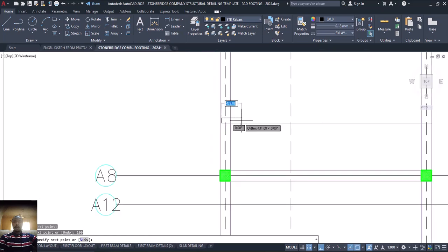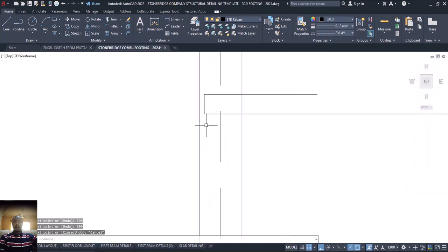Then come inside. Now this inside is what? 600. That's 50D. Is that okay? 50D. So I will now press my what? 600. Is that okay? Enter. Is that okay? At this edge. So now if you look at this one, if you have 25 down plus 100 plus 25 up, that's cover. It gives us what? 150 in total. Is that okay?